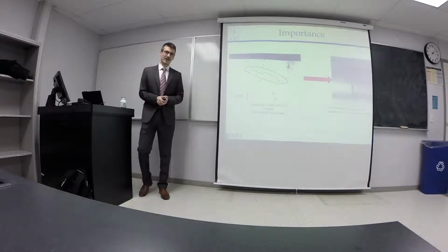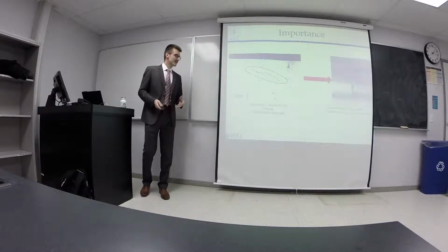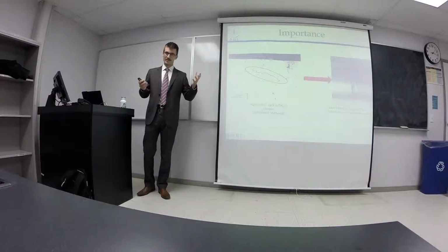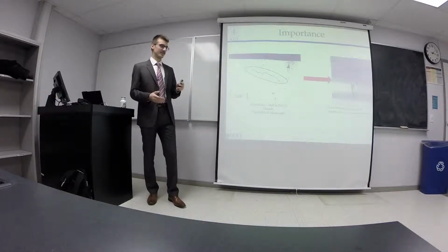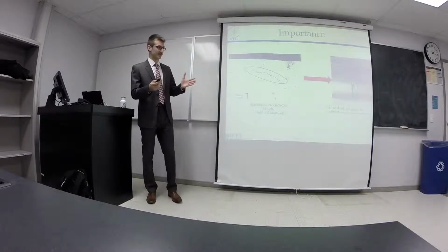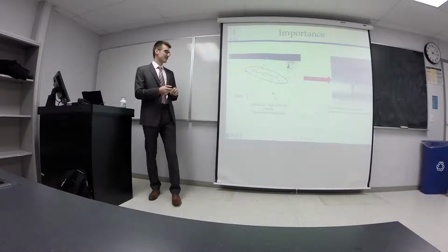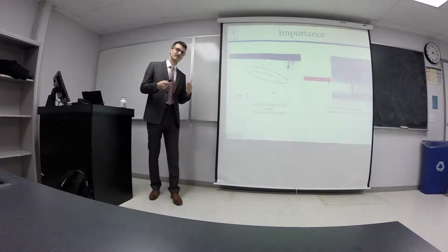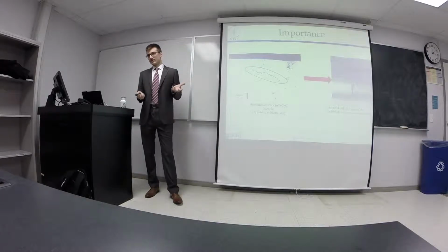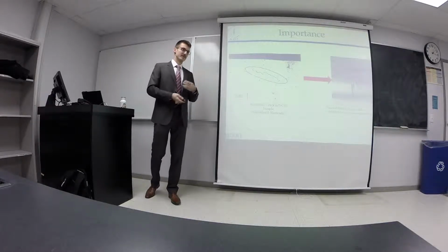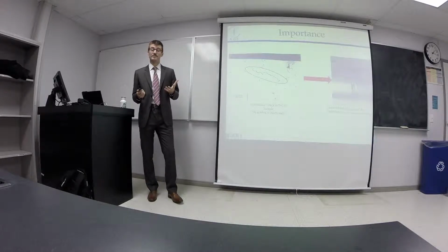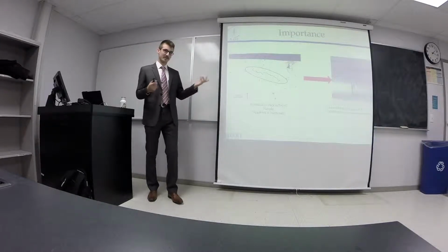So, subsurface cracks. What are they and why are they important? On the left here, you can see circled in red is a subsurface crack. This is a void or an imperfection in the material that was formed either through the manufacturing process or some impurity, something like that. This essentially lowers the overall strength of the material. These are important because they can later develop into surface cracks, which in the industry could lead to piping failures and all that. So it's important to monitor these to form an effective aging management program for key components in the nuclear power industry.